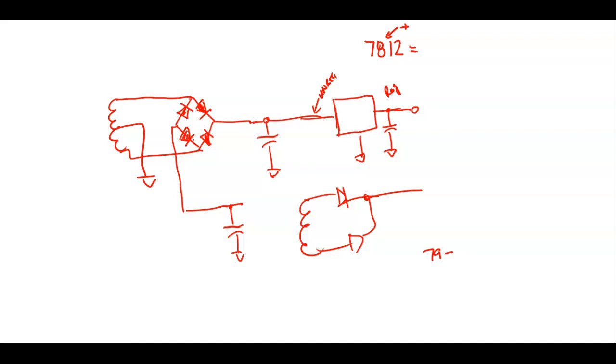What do you mean? Yeah. So over here, we would come in like something like this. So I'd point my cathode toward the input. Let's just do a half-wave rectifier. I would come over here and I might put a resistor there, and I would put my Zener in the circuit like this. And then this would be my output, right? And then we'd have a filter right here. So this would be the way the Zener regulator would look. And this would be a negative regulator.